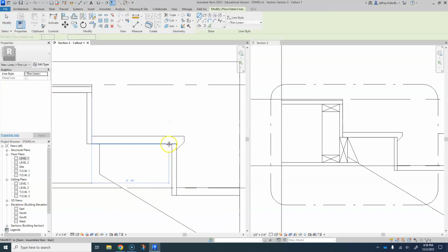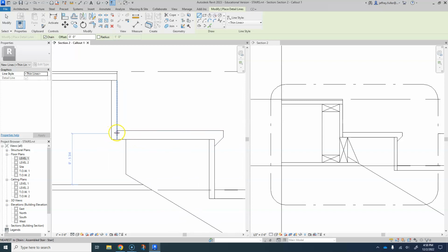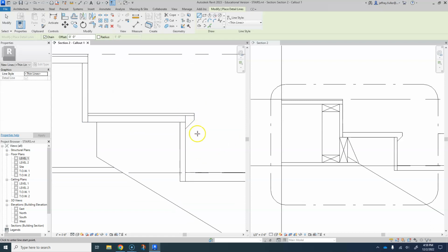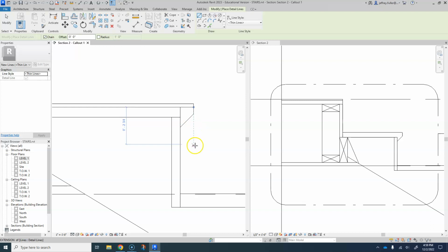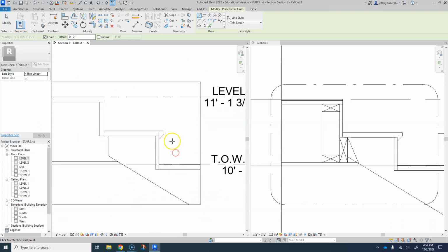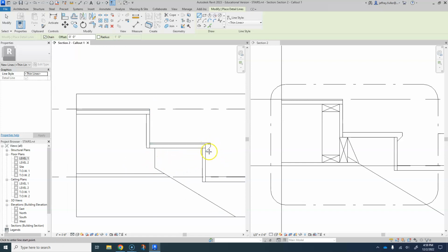Okay, and we'll come right here. I'm going to come 1/4 inch down, because this is going to have the same floor material. I'm going to put the same floor material right on top of my stairs. I'm going to put a line right there, because that's going to be a nosing. They're going to actually cut that independently, and they're going to cut that on the site and put it up there as a nosing. It's going to be a solid piece of wood.